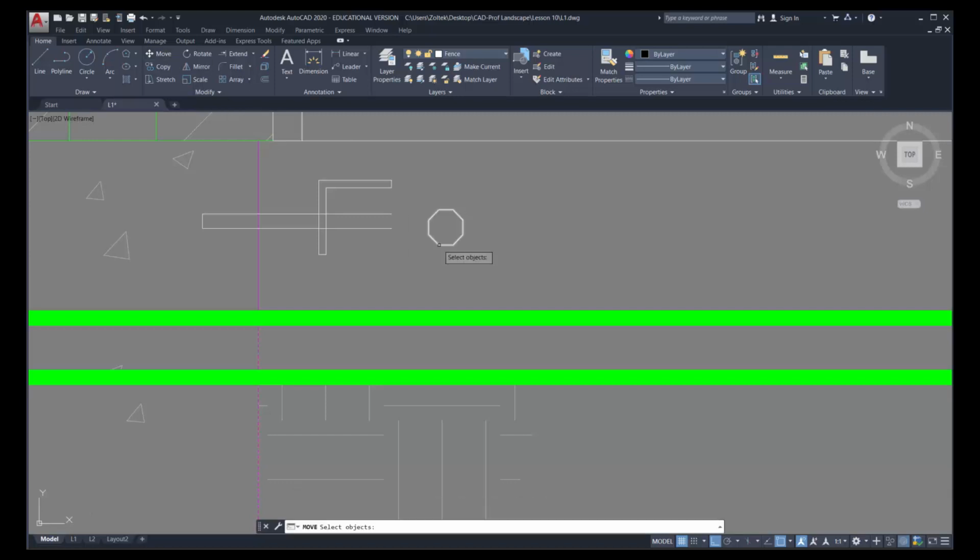So now I'm going to move the bolt head so it's centered onto the actual threaded portion of the bolt. I use the mid from 2 points. I'm going to also place it in the middle between the actual threaded portion. Now I can take the information I already have there and copy it. I'm going to copy this line from this endpoint to that one to this one. I've shown all of this in red on the actual PDF file, but we can do it this way. And the head itself is a 1/2 inch thick, so I'll offset it by 0.5. And this line offset now gives me all the line work I need.